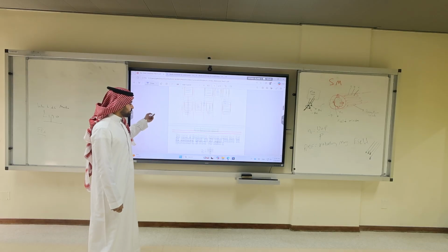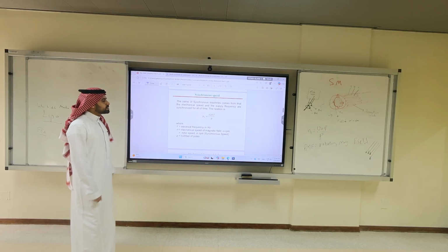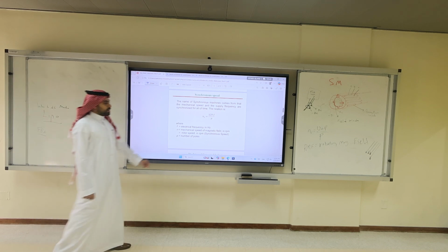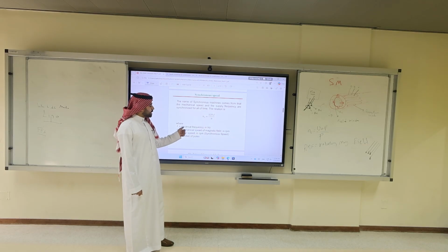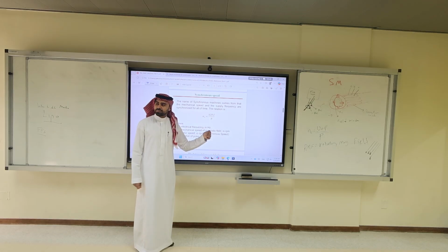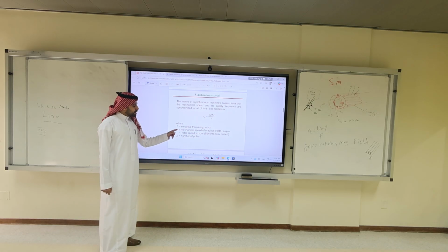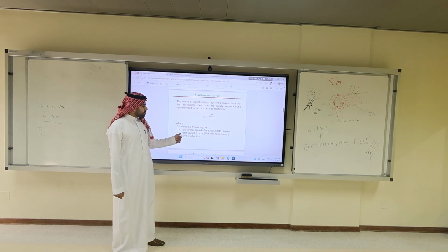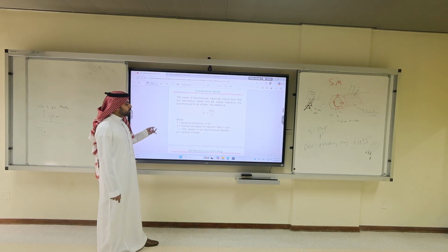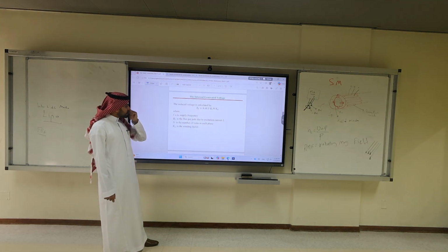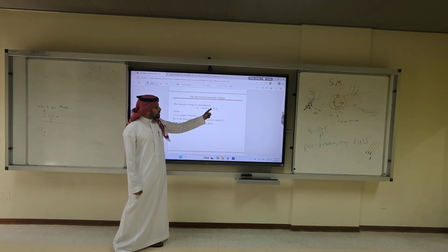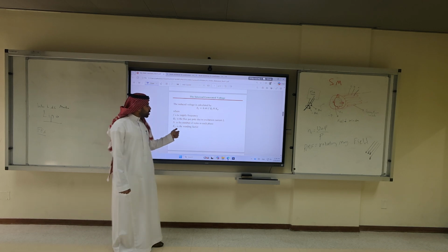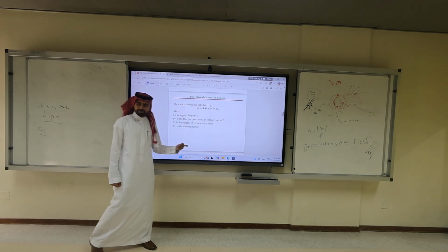So we have 5 minutes left. Let's revise a couple of concepts. If we increase the number of poles or increase the speed of the machine, we change the frequency output. So F has to do with the electrical frequency in the terminals of the stator. N is the mechanical speed or rotor speed, synchronous speed, and P is the number of poles. We remember this. We also remember that the induced voltage is 4.44 times the frequency times the flux times the number